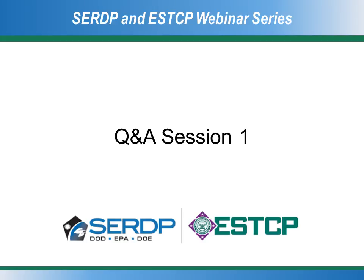So if you're running a survey across a site that you know is extensive in one direction, and you want to get a cross-sectional view, but you know that it's, for example, a plume, and you know it's pretty extensive down gradient, then maybe there you're pretty safe. You can assume that the 2D assumption is approximately okay given the purposes of your study and your specific site.